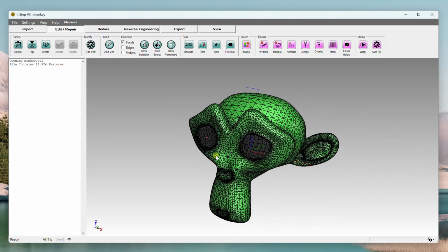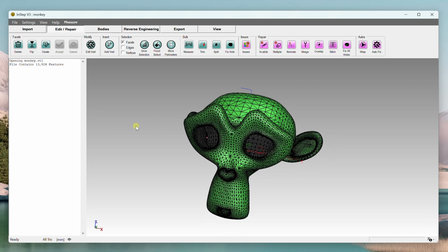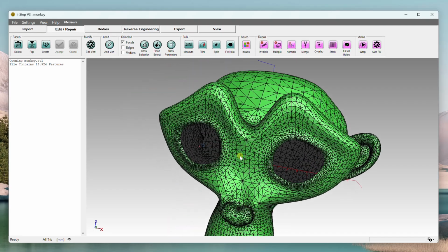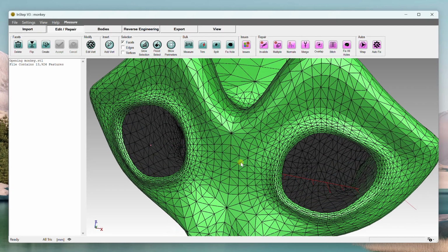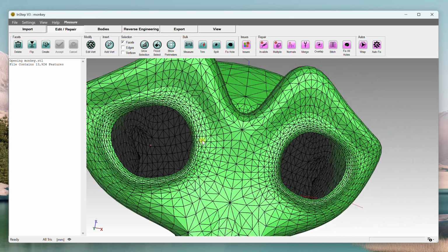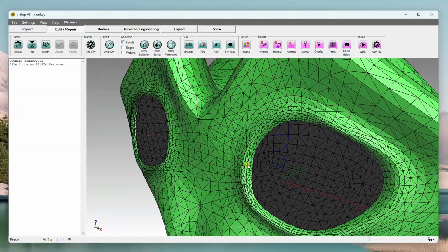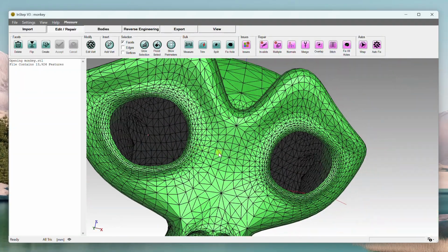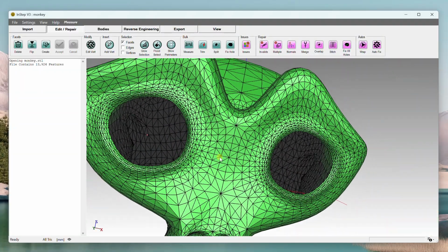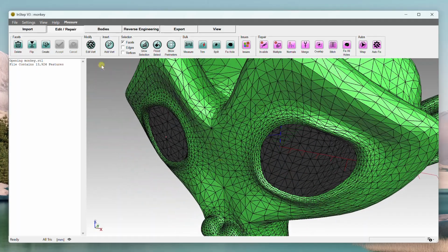And that pretty much covers everything on the edit tab. There's not too much else. One thing to point out is when you do low level edits, so deleting stuff, the only thing you can delete are facets. Both edges and vertices are only deleted during export or import because there's no valid data associated with an edge in terms of STL files anyway.